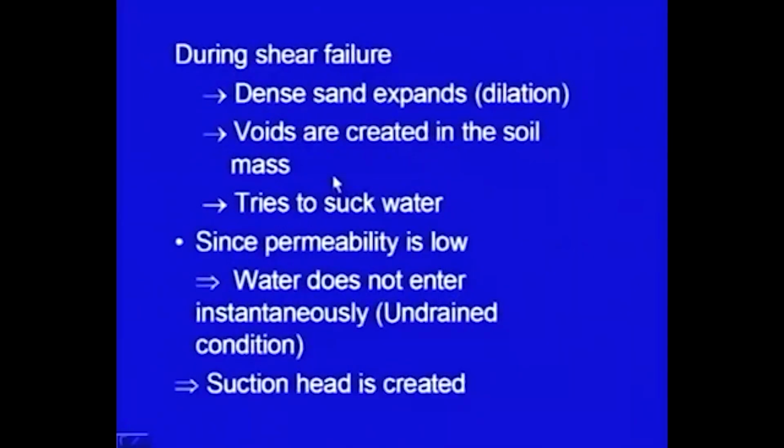Let me explain why this correction is applied, what is the phenomenon, what is the basic concept behind this. Now, we have already discussed that it is dense sand or silt, fine sand. During shear failure, as you remember, the soil is failing because of the cutting shoe. At the time of failure, if it is a dense sand, then it will dilate.